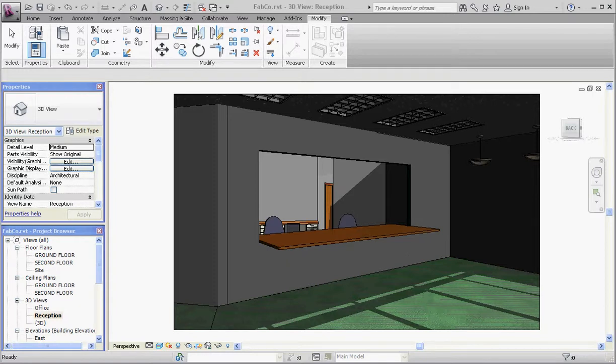So in this video I'd like to show you a couple different methods on inserting a countertop on a wall. The one method that you're looking at here is where we've taken just a regular wall and made a cut inside that wall of specific dimensions, of course, and we put a countertop element into that. And another way is just take a wall and make it go up to the countertop level, maybe 36 inches tall, and have it terminate there, and then put the countertop on top of that. So let's explore both of those methods.